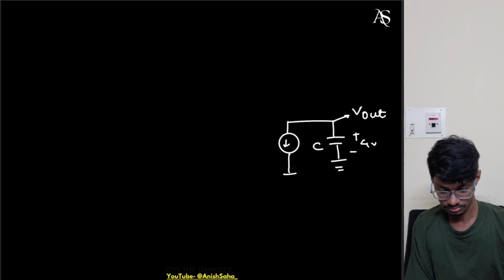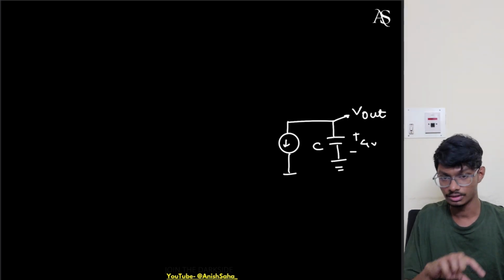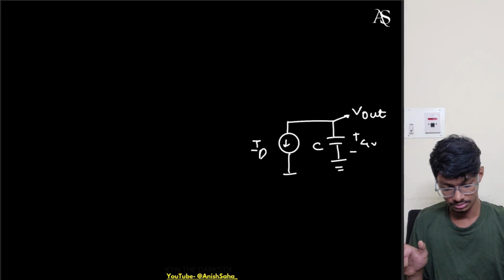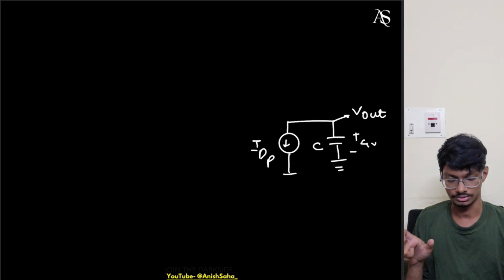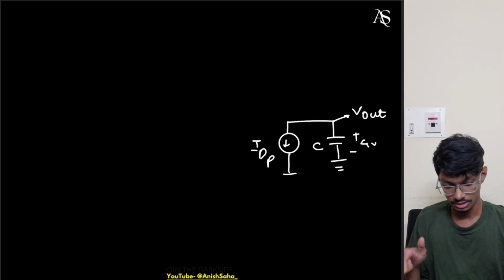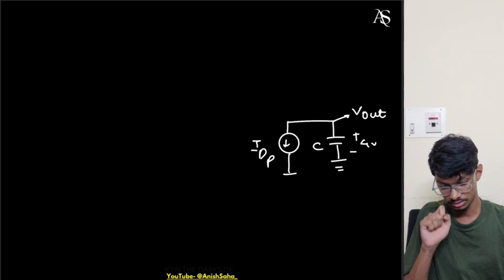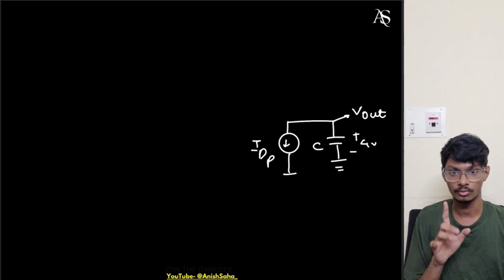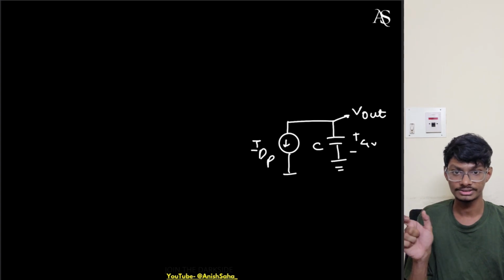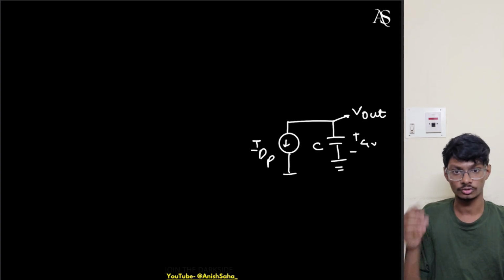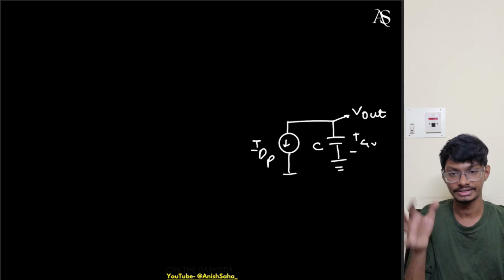This is V out. So this capacitor will discharge through this current source, right? To how much will it discharge to? So when will the PMOS be off, right? PMOS will be off when the VSG is less than the VTH, or it is equal to the VTHP.